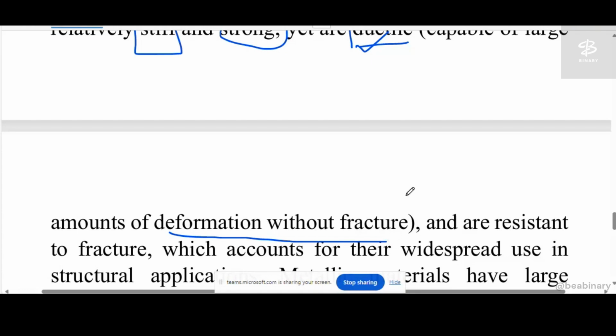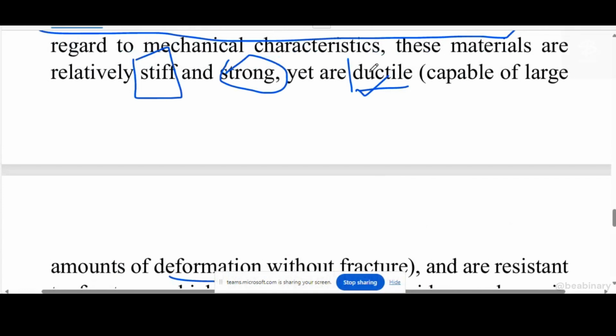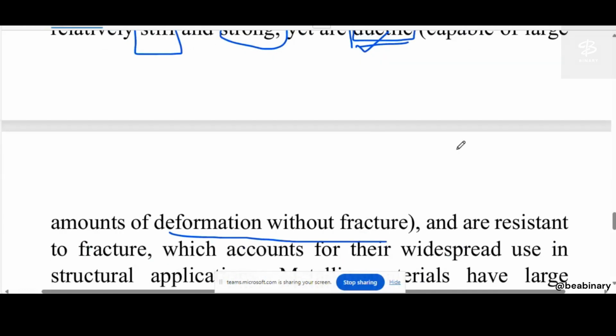But here we are talking about elastic deformation, and plastic deformation. In ductility we are talking about general deformation. Elastic deformations are allowed in engineering, but plastic deformations are not allowed. Once the plastic deformation starts, we consider that the material has failed. Though the material has not failed, in engineering applications they will consider it a failed material. Though it will resist the load as well, and after some time it will fracture and crack down.